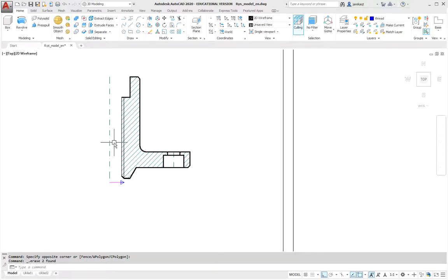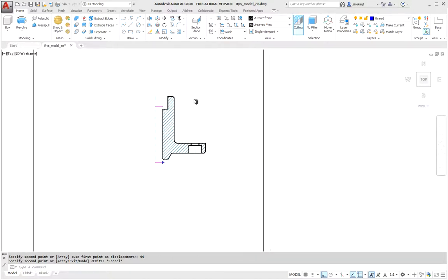To create this thread well, we will need the upper position of this radius. So we copy this radius and copy it by an even number of strokes. In this case 44 should be enough. Why should it be like this? Because the thread will start earlier than the solid and end higher in relation to how we will enter the material of the solid. It will be a smooth transition. And now that we have the body ready, we are almost at home.